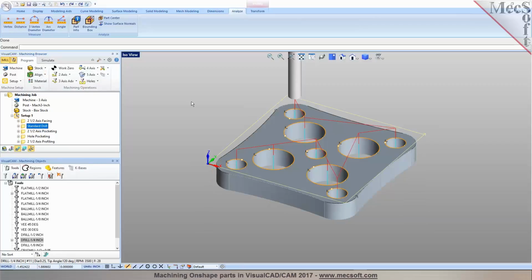Okay. And it doesn't automatically pick the drill by looking at the geometry. I, as the operator, have to pick the drill size. Is that correct? You would basically specify the tool size. Now what we also do is feature detection and machining. That is the next thing I'm going to demo to you, where it'll identify all the hole sizes and everything, and based on features, you can then choose the operation and the tool to machine it. So in this case we are manually programming it, which is the conventional way of doing it. Okay.